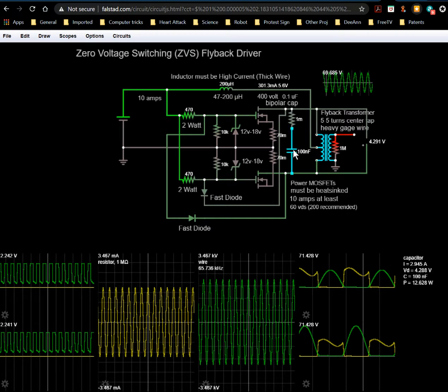And this is why it's important to not use an electrolytic, at least a DC electrolytic, because you'll blow it up, because once this thing reverses, you've got plus and minus here. Once this is fully charged up, it'll start trying to dump its energy back into this magnetic field, okay, flowing in this direction, right?